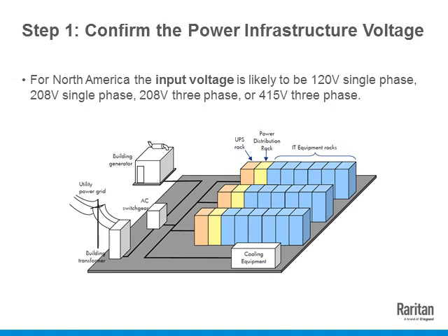The newer data centers where the higher capacity needs tend to trend towards 415 volts three phase. That's been the trend we've been seeing in the past 4 to 5 years in high capacity compute environments. So determining the right kind of power infrastructure that you're going to put in place on a new data center will give you the maximum flexibility in terms of handling the ever-increasing need to move capacity up, while keeping all the different configurations within your data center for the applications you have today.